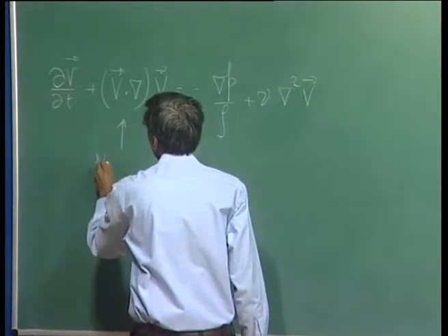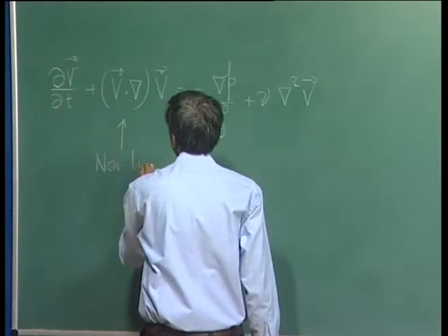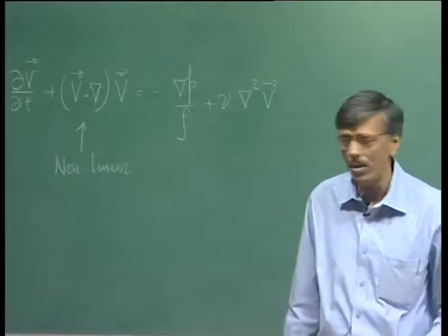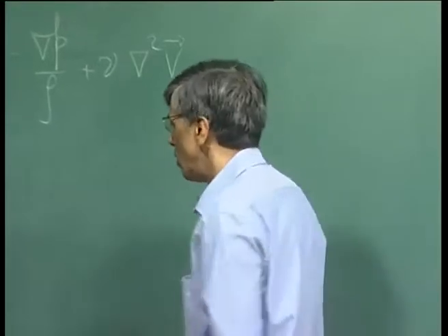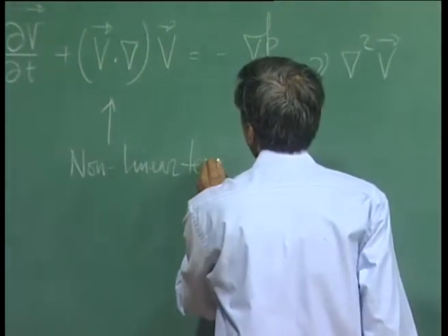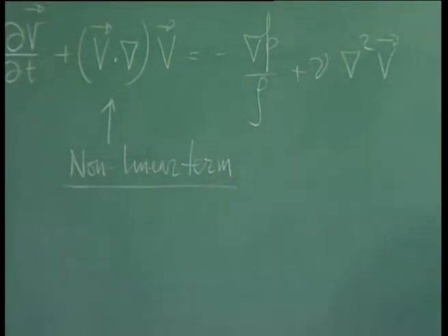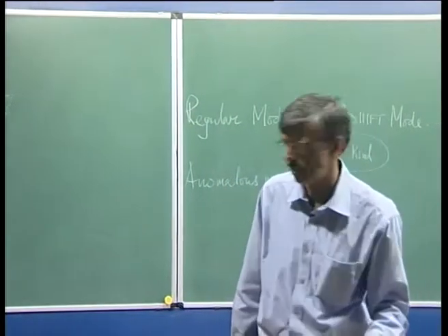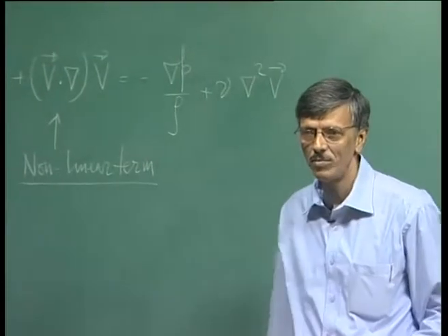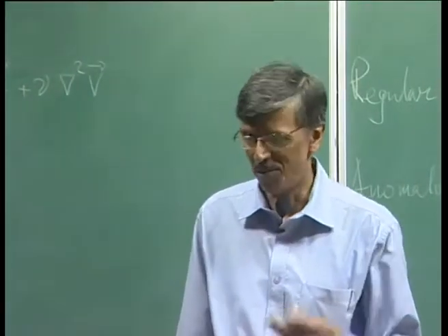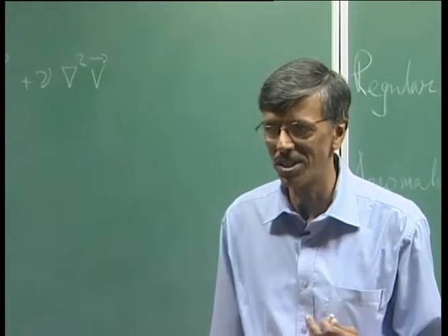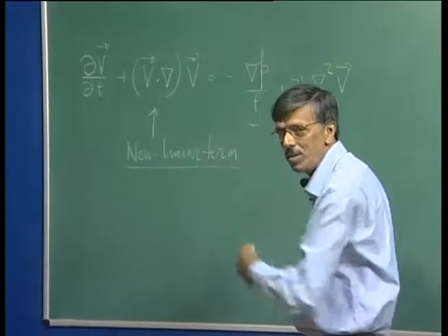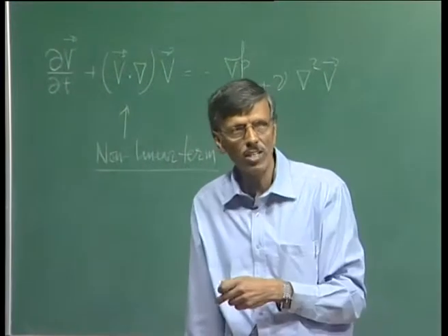Of all the terms that you see, this plays quite an interesting role. This is your nonlinear term. Well, if you are a mathematician, you would say it's a quasi-linear term, because the highest derivative is second, and that's why it's linear. But this is a nonlinear term that plays a significant role in determining the dynamics. We have already seen that all instabilities do start up from here. Why? If you recall, we have written down the Navier-Stokes equation in rotational form. What happens? I can write it down in terms of v cross omega and gradient of v square by 2.